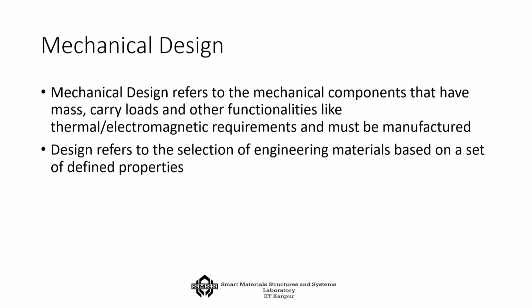Now, we need this for mechanical design first, because later on we also have to carry out an electrical system design in terms of sensors, actuators, microprocessors. I will come to it later on, but our first focus is mechanical design. So, what is this mechanical design for which I have to choose the material? Of course, mechanical design refers to the mechanical components of a system that have some mass and have to carry some loads. In other words, it should be able to sustain some loads, and maybe additional functionalities like some thermal requirement, some electromagnetic requirement, and also, at the end, do not forget that it has to be manufactured. The design now has to give birth to a complete product; you cannot keep it as a concept.